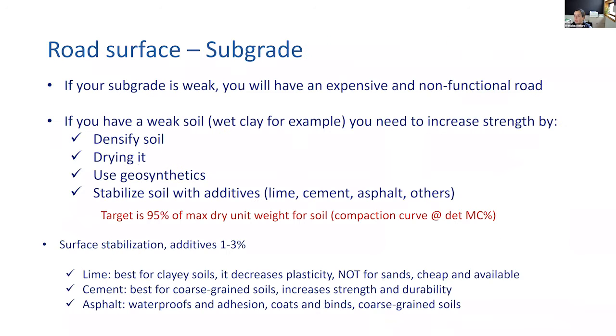So one of the things that I always like to talk about is subgrade. Whether we have a dirt road, which is the subgrade in itself, or we have a layer of rock on top of it, the subgrade is, I would call it, the foundation. If you think that you're building a house, your foundation is very important, right? So in the road world, the subgrade is the foundation of the road. So if you have a weak subgrade with a weak soil, you will have a very expensive road, and it will be non-functional because you're always going to have to be repairing it.